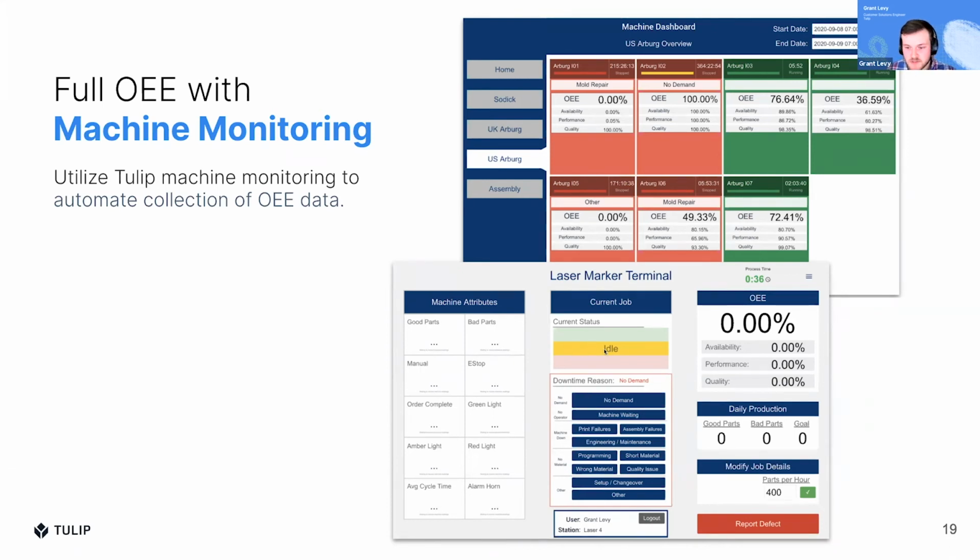So right now, this machine is listed as idle because its downtime reason is no demand. Idle states are another kind of addition to OEE. Maybe it's an expansion on OEE where no demand would mean that you're really not scheduled to run anything, so you don't want that metric to go against your availability. But you can see here, there's a bunch of different buttons to indicate a particular downtime reason, and that can ultimately feed back to some of the metrics that we see here.